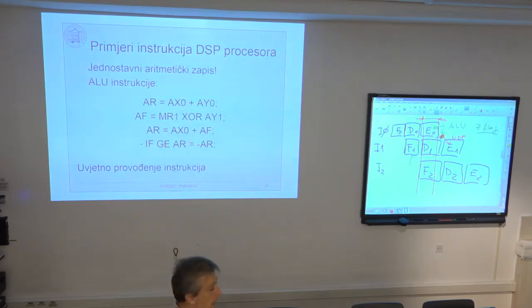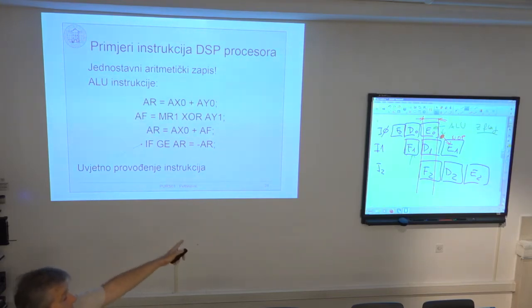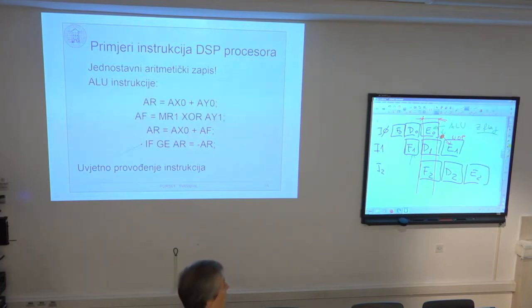In this case, the CPU core automatically inserts wait states into the pipeline as soon as it resolves these dependencies. So it knows that maybe the next instruction depends on the final phase of the previous instruction, and in this case it has to wait. It inserts wait states into the pipeline until all of these conditions are met, and only then can it execute the next instruction in sequence.